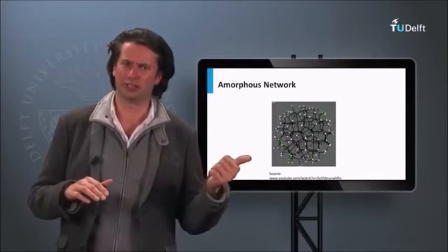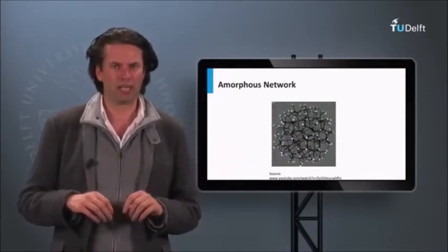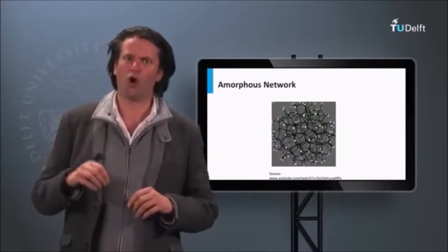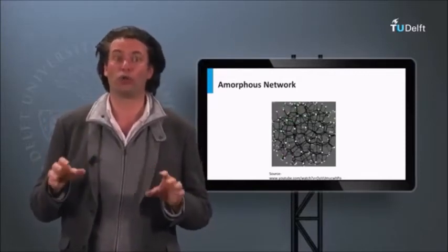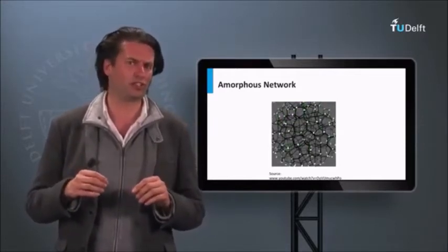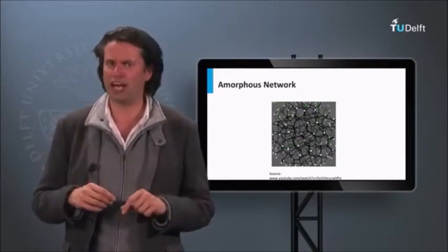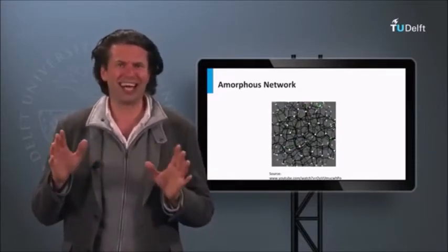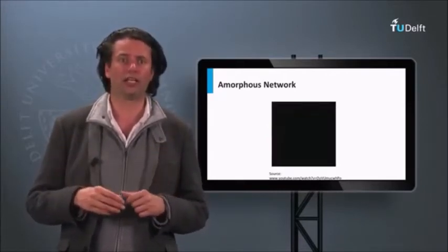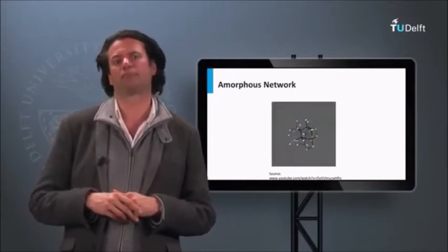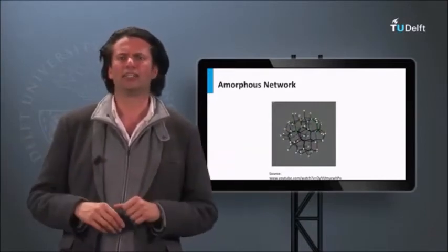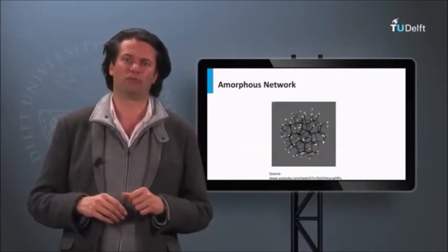The lattice is disordered, as you can see in this animation. The animation shows the growth of a so-called continuous random network. On atomic length scales, also called short-range order, the atoms still have a tetrahedrally coordinated structure. The silicon bond angles and silicon-silicon bond lengths are slightly distorted in reference to a crystalline silicon network. On short-range order, the lattice still might look very crystalline-like. However, at larger length scales, also referred to as long range, the lattice does not look crystalline anymore.